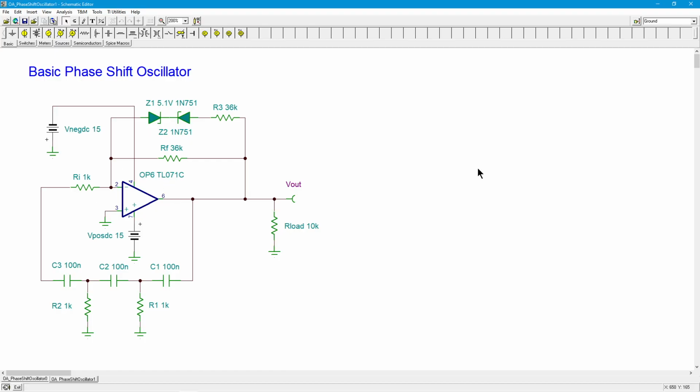It doesn't stay at minus 180 forever, right? So because of a few extra degrees, that's going to shift what we really need down here. But this will sort of self-select, because there will only be that one frequency that gives us the appropriate gain and the appropriate phase shift, right? Because we just need 360 total.